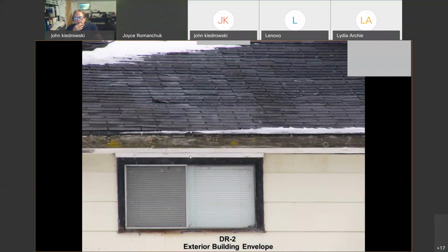Take a look at another. Okay, we take a look at the fascia board. And we take a look at the condition of the wood framing on this window. And depending on the type of window, it's probably a window that should be upgraded. Looks like a sashless slider type, which is not very energy efficient. But when we start looking at the materials and the damage that's been caused over time, and look at the condition, certainly it gets a lot of telltale signs of moisture and water that can penetrate